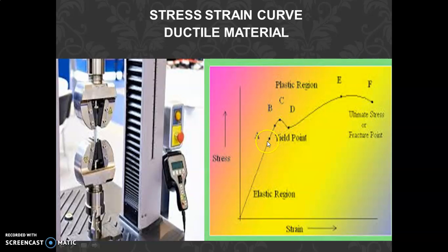So this particular stress is directly proportional to strain, and this happens up to the elastic limit. So up to the elastic limit we may consider that the material remains elastic in nature. So it will regain its original size and shape. Up to this point, if deformation happens, then the material regains its original size and shape. Is it okay? Then coming to the next point, this is the upper yield point, and here it is the lower yield point.